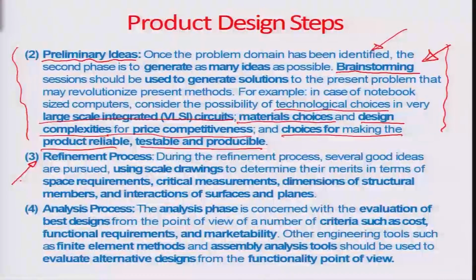The next step, once this ideation process has been done, is a refinement step, where realistic decisions have to be taken. Here is the refinement process through which several good ideas are pursued out of whatever idea rack has been generated in the last step, and the refinement can generally happen using scale drawings to determine the merits of different ideas, maybe giving a quantitative scale to the merits.